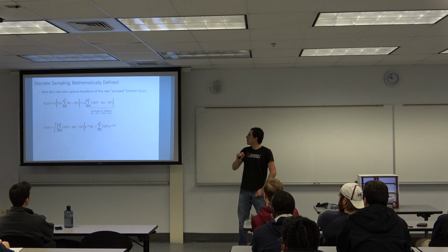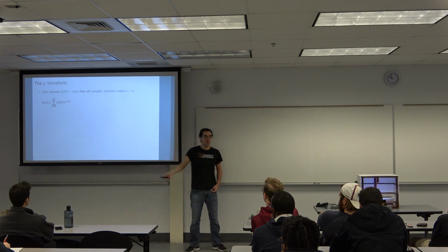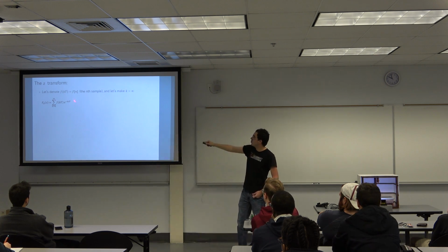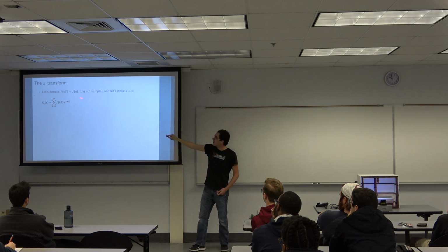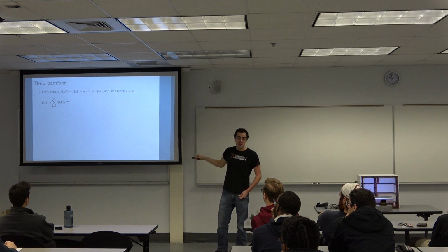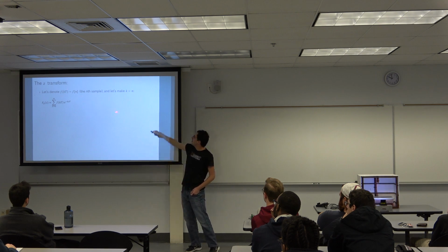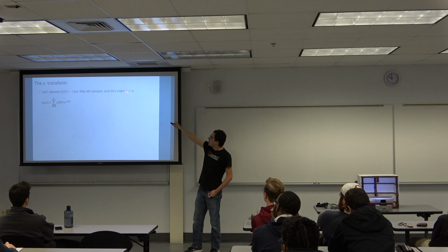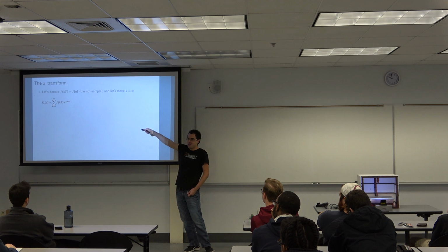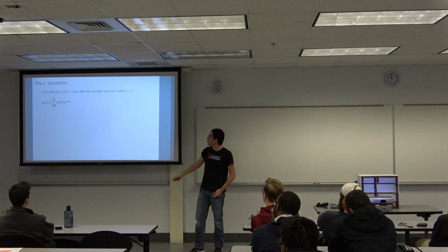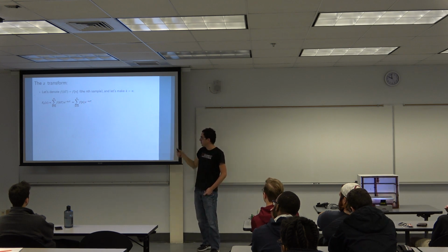And we're almost there. The only thing we need to do now, to go back to the textbook definition of the Z-transform, is to replace f of kT by f of n in square brackets. It's not that n is kT; the square brackets mean the nth sample of f in the discrete domain. And let's just replace k by n, which we can do, but bear in mind that this n is not kT, it's just k. So if we do that, we get the nth sample of f times e to the minus nsT.